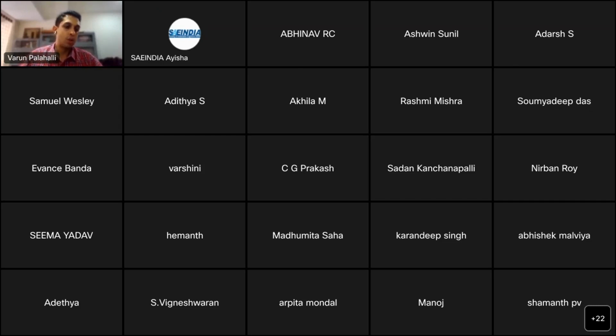Sure, sure. Like you saw even in the presentation that I was doing, I used the frame in aluminum, but you don't need to have every single component in aluminum. You would create a material of aluminum for certain parts. You would have composites applied for certain parts, maybe carbon reinforced polymers. You may have steel where you have high abrasion, such as your landing equipment.